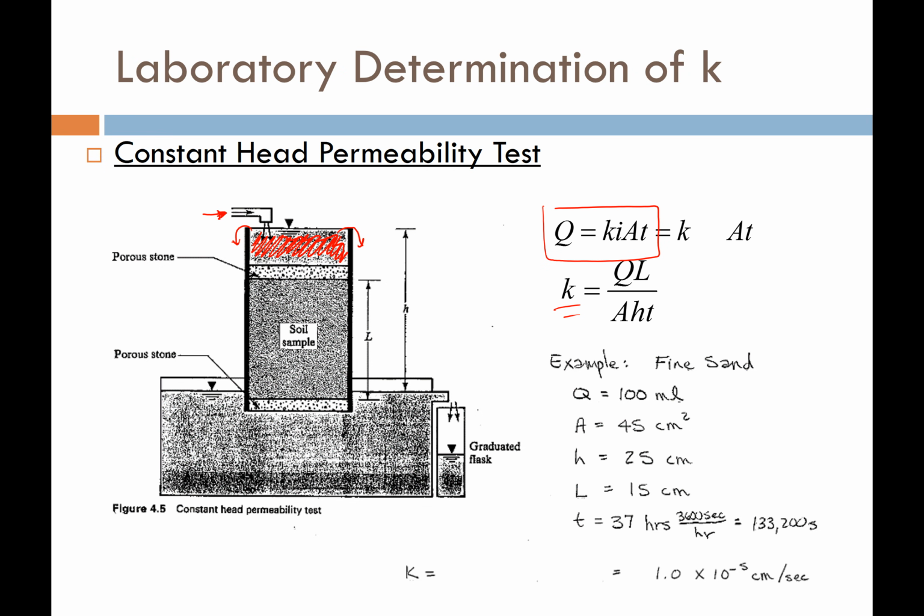That water is going to percolate down into the soil and eventually saturate it, and it's going to go down into this lower chamber. This lower chamber has a roof placed upon it. It's sealed, so water can't get out. We do that so that we can control the elevation of the water, or the total head, in the lower chamber.